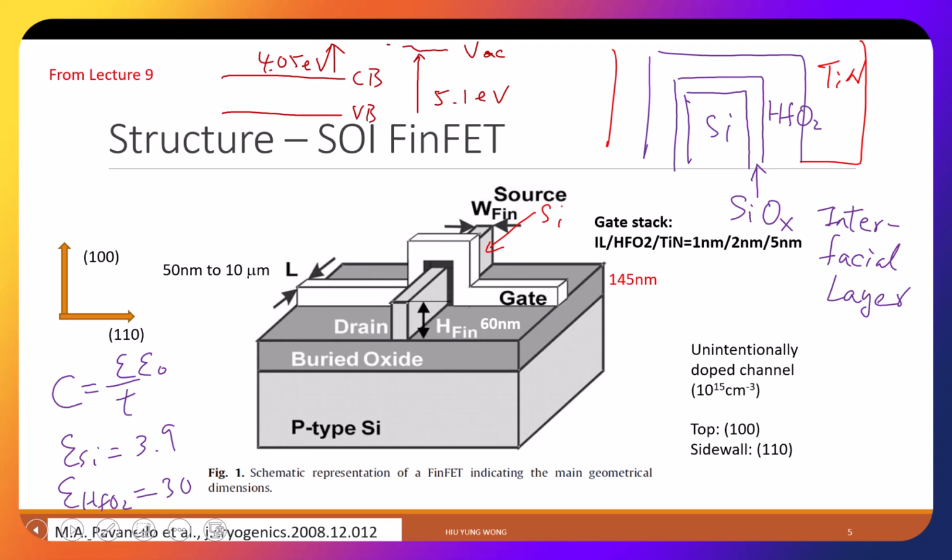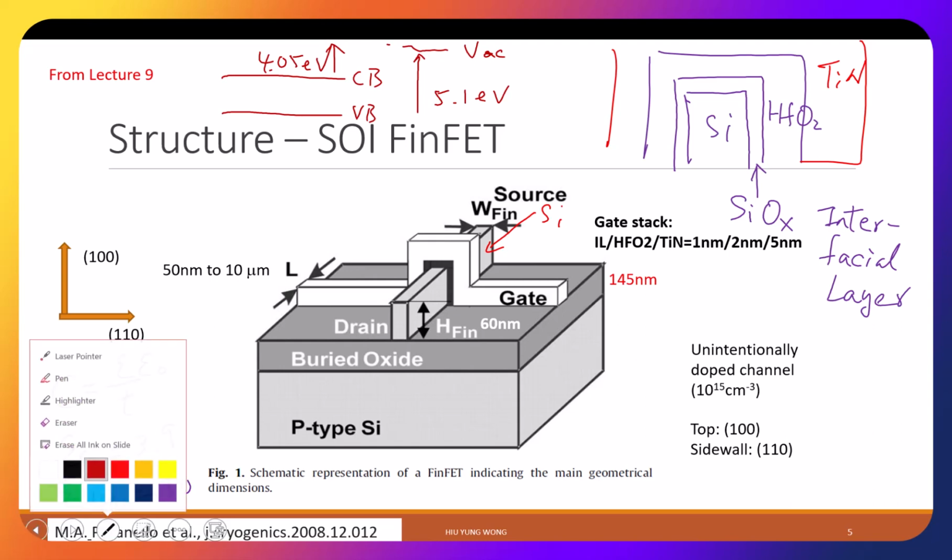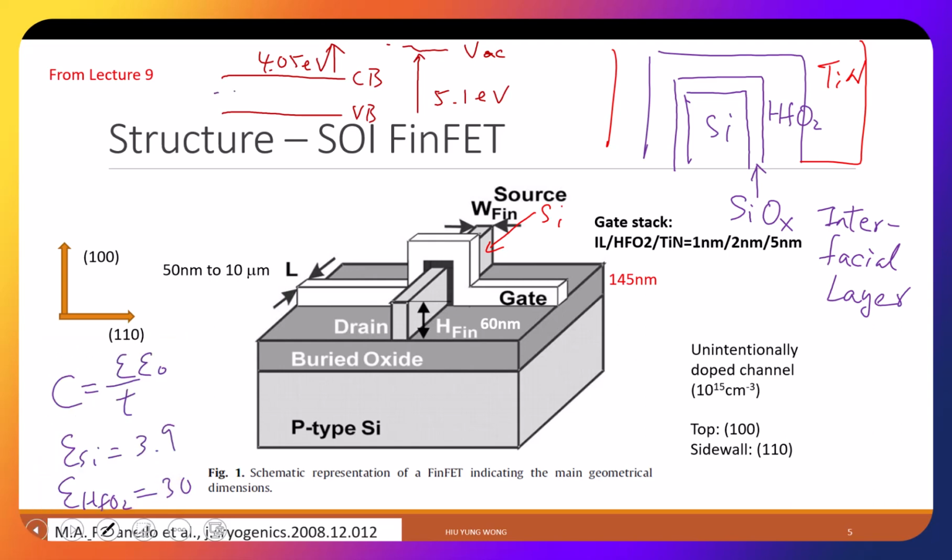And what is the meaning of mid-gap? It means that I want to have a work function about 4.5 eV. That is what you mean by mid-gap if you read papers. A work function that has an energy about the mid-gap of silicon. It just means that it's about 4.5 eV, 4.7, 4.4, instead of 4.0 and 5.1. Okay? So I hope you understand this, yeah?